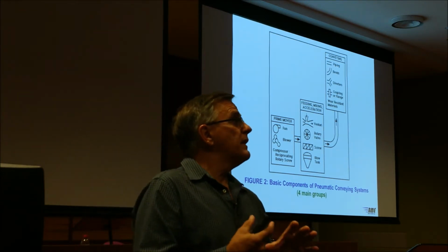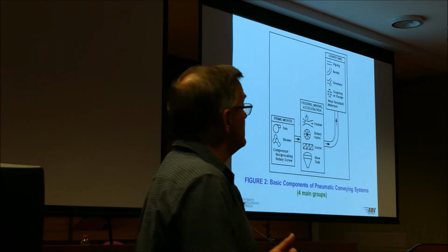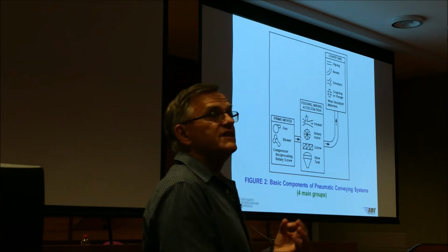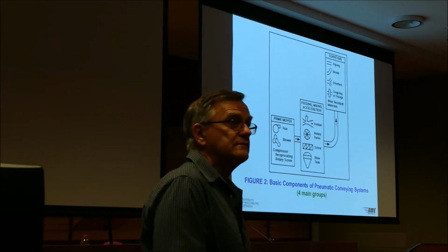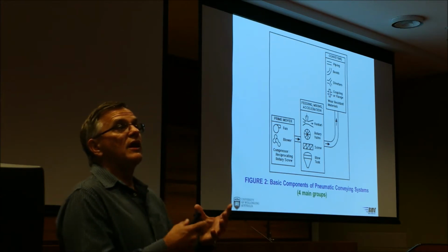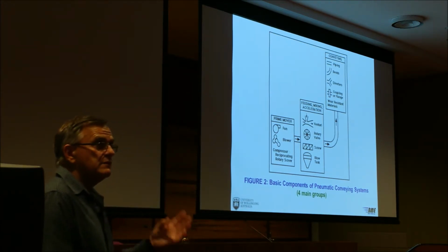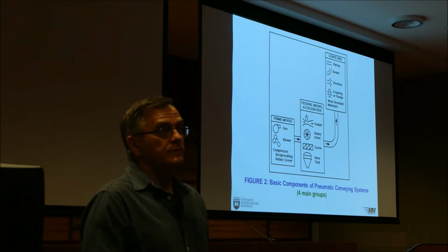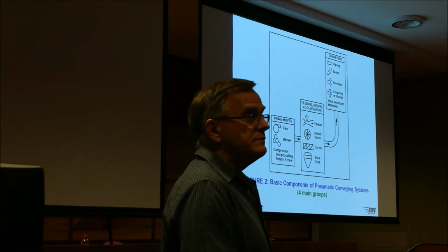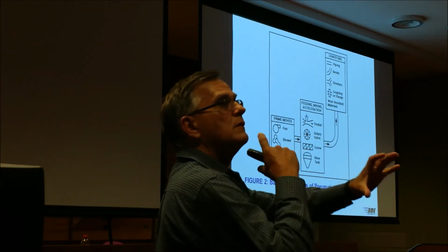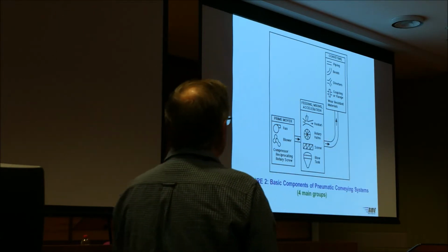So you talk about in this industry, those industries, in food and chemical, CIP, which is clean in place. So the couplings have to be CIP rated, so there's no residual material at those connection points. So you've got a nice smooth bore from pipe to pipe or pipe to bend.